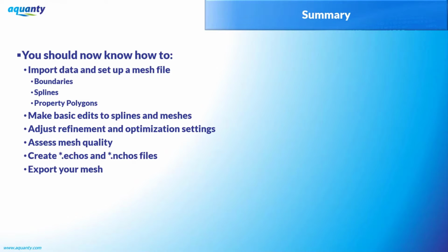If you import a polyline that delineates the entire model boundary, then you can right click imported objects and use the select along polyline option. But that would select all the nodes for the entire model domain if it was defined using one single polyline.